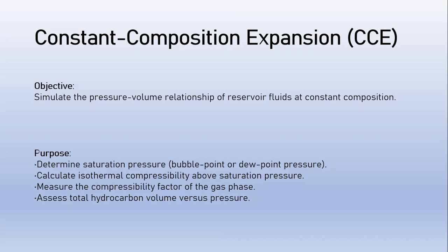Also to calculate the isothermal compressibility above saturation pressure, also to measure the compressibility factor, which is Z, of the gas phase, and also to assess the total volume of hydrocarbon with respect to each pressure step from initial to atmospheric pressure.